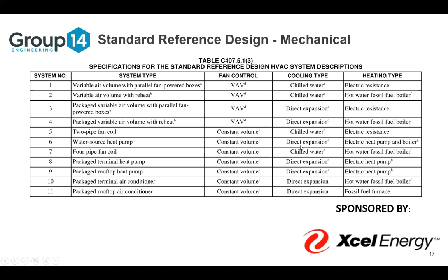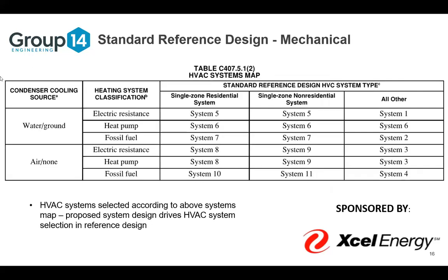So you'll see with an air-cooled chiller, you're going to get a lot of savings if you select a highly efficient air-cooled chiller, because your baseline system is going to be a DX coil. Now, if we had a water-cooled chiller, again, we're up in this chart now, and we're looking at system 2.